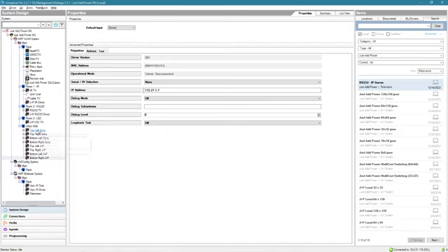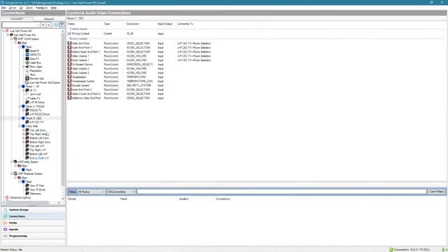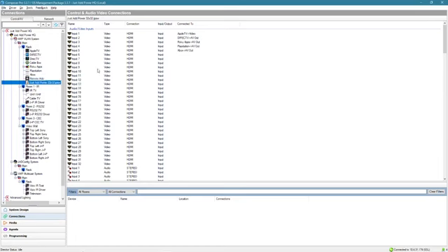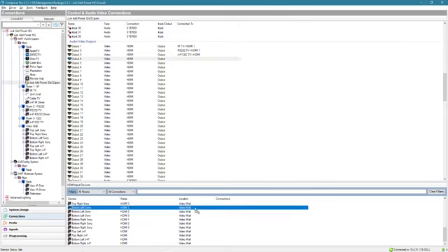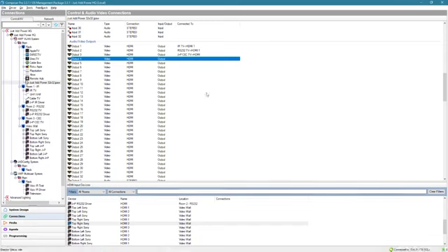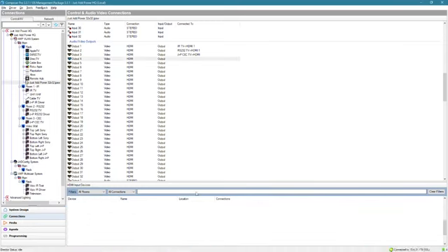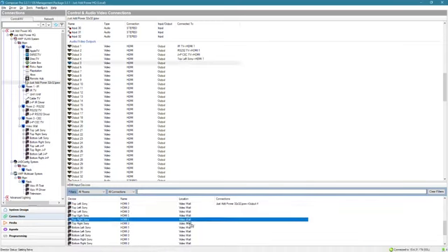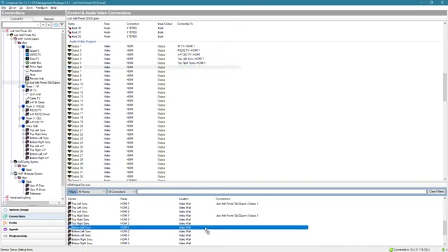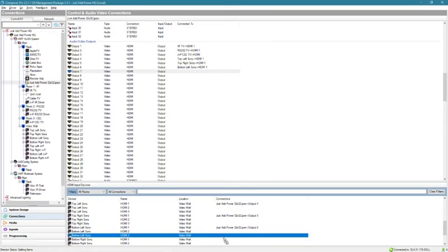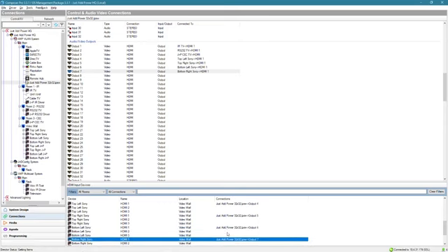And then we have to also connect this to our switching driver because these are new displays in our system that didn't exist before. We're going to go down to outputs. We got output number 4 is our top left Sony. Where's our top left Sony? Scroll. There it is. Top left Sony. And we've got our top right Sony HDMI 1. Bottom left Sony and bottom right Sony HDMI 1. So there's our outputs connected.